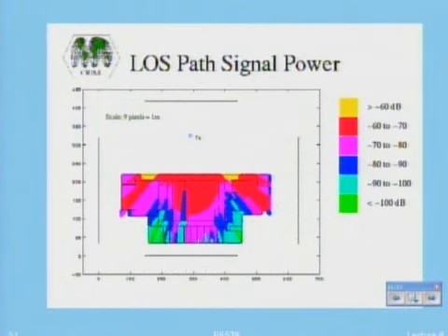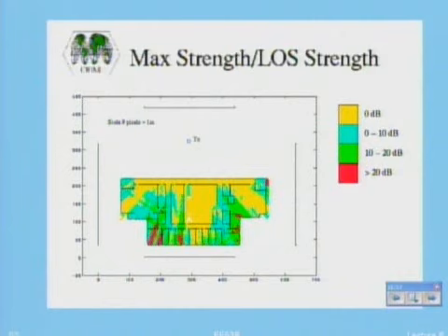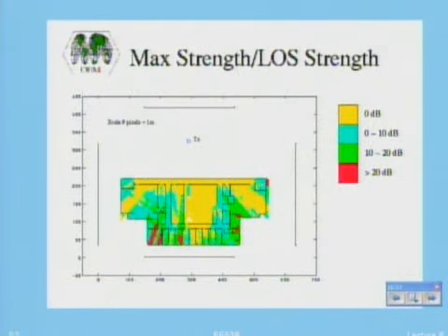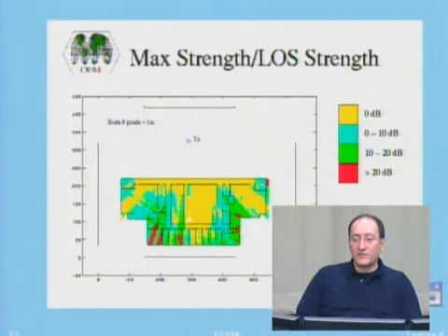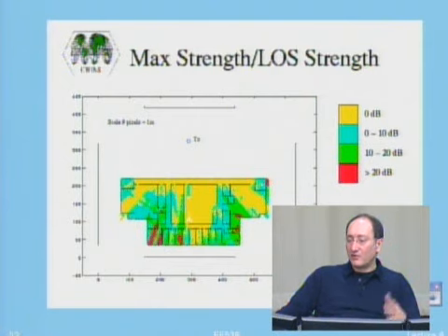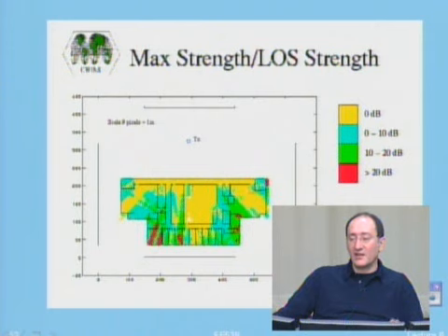These are path loss results, and again, results of ray tracing in a variety of different scenarios. Ray tracing is very good for creating these color charts for whatever you want, such as the strength of the first path, or line of sight for obstructed lines. If you want to get the individual paths and analyze them, ray tracing is very useful.